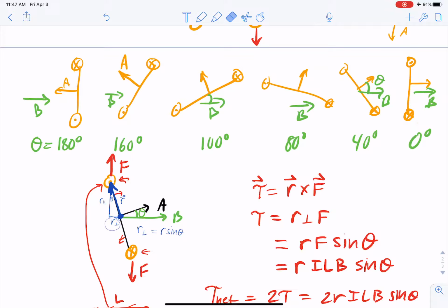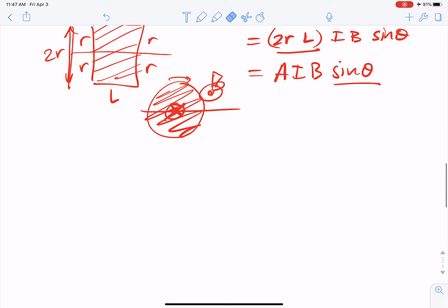It used to be mechanical. There's like fancy ways of hooking the wires up from the loop to connectors. It was all very natural because as it rotates, you connect the other way. That method is essentially like this. You have your loop with the two leads of the wires coming out. You connect that to essentially a pipe. Okay, so you weld this into both of them, and then you cut the pipe in the middle. Okay, so that they're not electrically connected anymore.